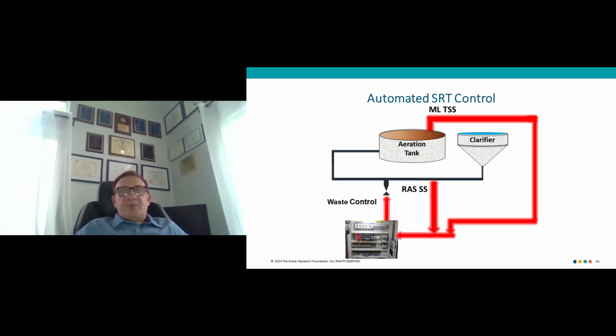The best approach of providing precise SRT control is to continuously adjust waste flow based on constant SRT criteria. The automatic SRT system usually utilizes total suspended solids meters, waste flow meter, and control equipment.